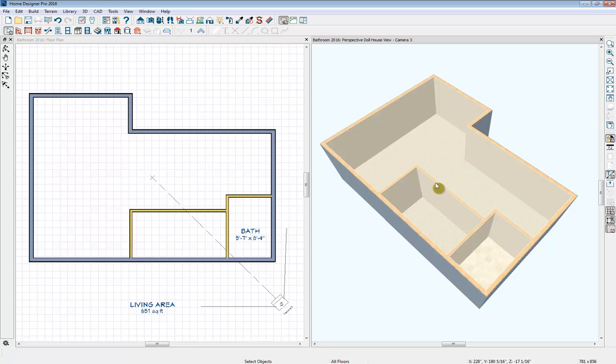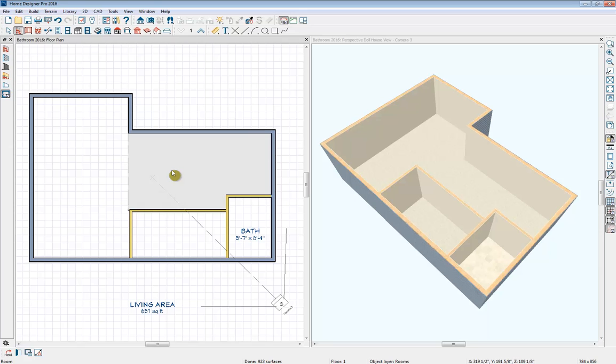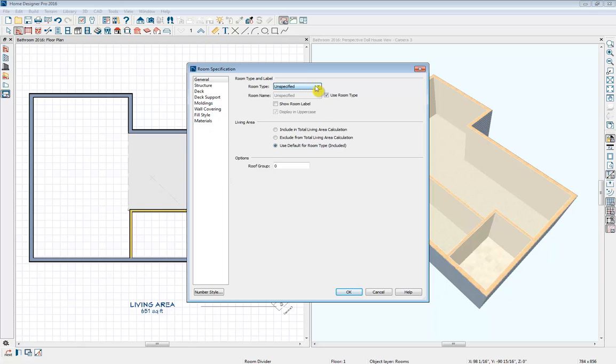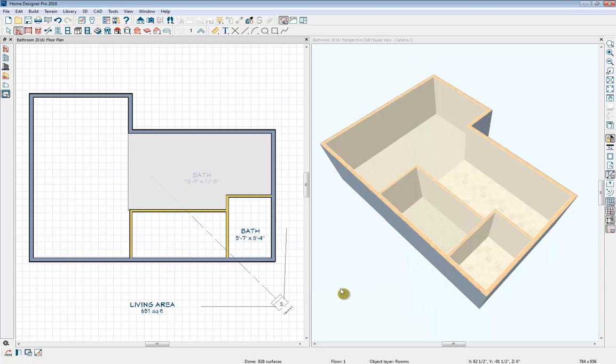For the rest of our bathroom space that we'll be creating in this section, I'd like to change the flooring in here as well. But if I single click in that area, it also selects all of the other space for the bedroom. So to do our change, I'm going to get right back into my floor plan, get back into my wall tool, and use my room divider. So then I can just click and drag, and that will create a divider without building any new walls, which enables me to open up this space and change our flooring in here or any other components that I would like to. Then we'll select OK, and that will update for us.